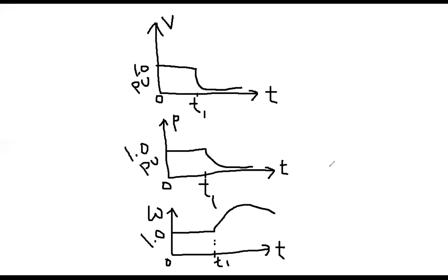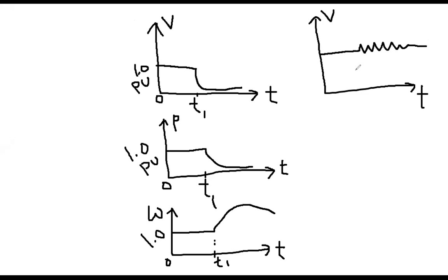So I'm taking you to the board once again. You see, we are discussing this thing. Now, if there is no fault involved, but the input torque is varying, so for example, this is your T and this is your V, and in normal condition, the voltage is going in that way. But if the input torque varies randomly, then there will be continuous fluctuation in the voltage profile. It is just the input variation. It is not the fault. That's why it will not go downward. It will just oscillate.